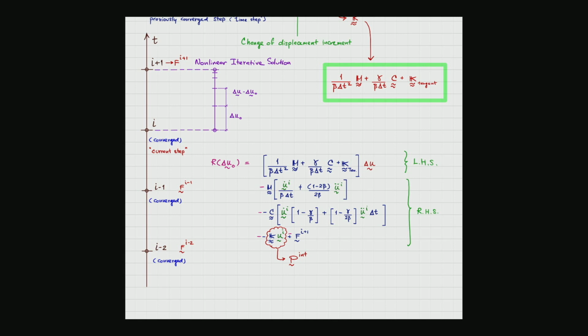But due to the cost of the calculation of the expensive element, that is not feasible to use for the small mesh, and then you end up with trouble about the memory, the RAM that will be used for the calculations. And it turns out that you can go with the cheaper element with the better discretization, and you might end up with a better result and faster calculation.